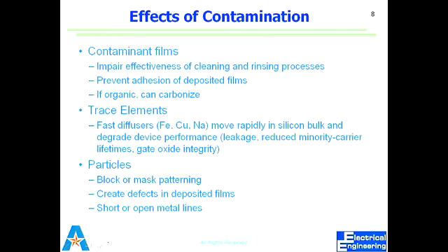And if I have silicon and I want to apply photoresist, and we discussed photoresist, we spin it and all that. So we know that photoresist will stick well to a silicon substrate, right? But if there is a film in there, it won't stick well. So that's a very simple example, but there are many more examples that we'll see once we get along. And some of the things can chemically change on the substrate. So that's on the films.